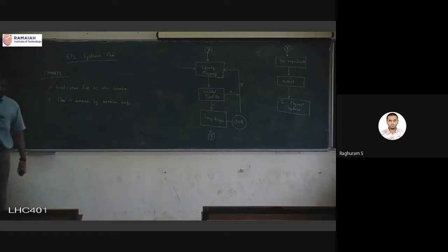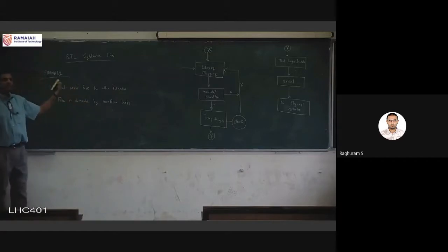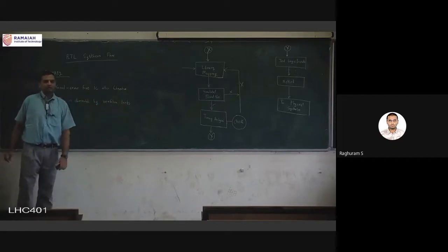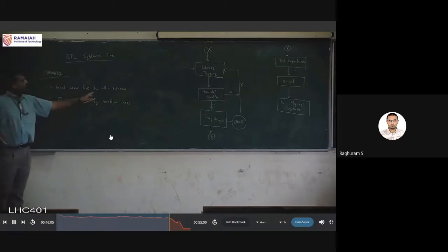The steps that aid in that are the verification tasks. Every step when we transform, we are doing a verification. We are doing a checking. If possible, when we are at the gate level, we are also doing formal verification. So these steps are the ones that are ensuring the error-free IC design, because an IC cannot be repaired.